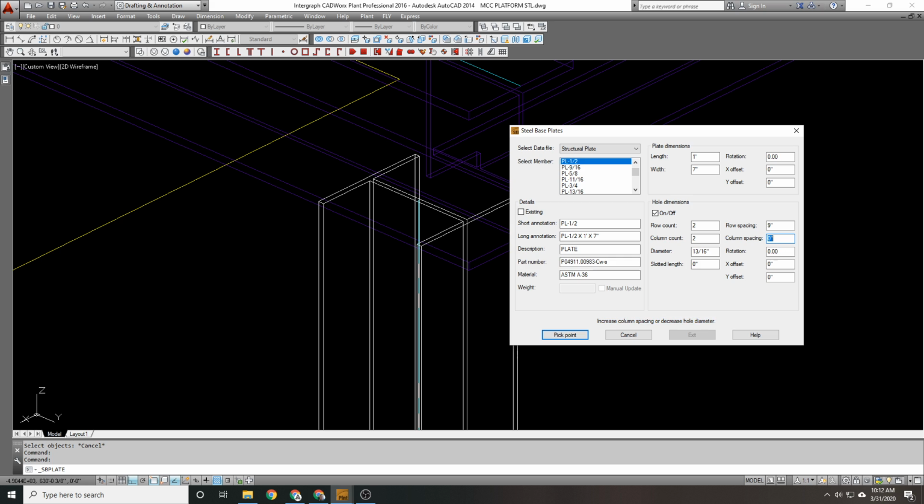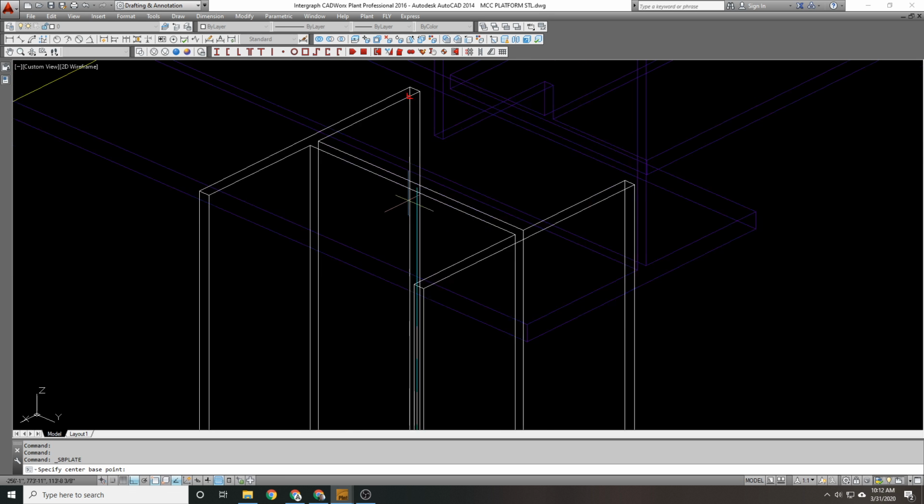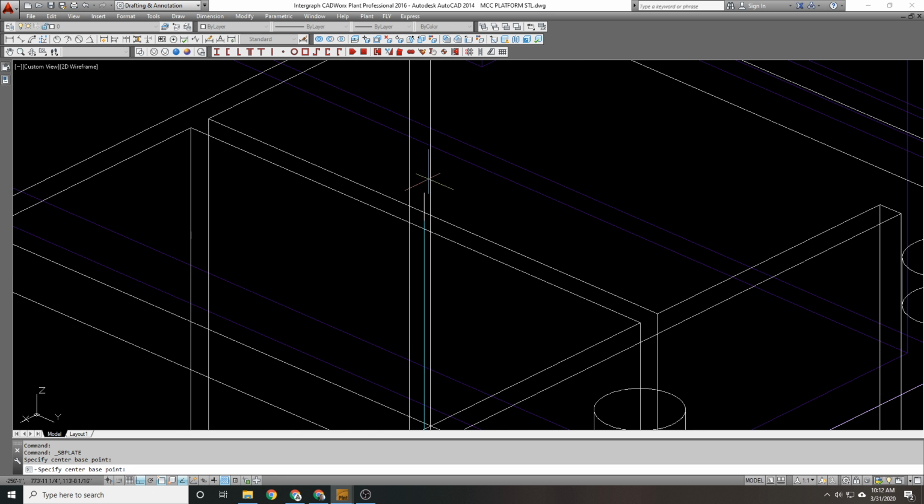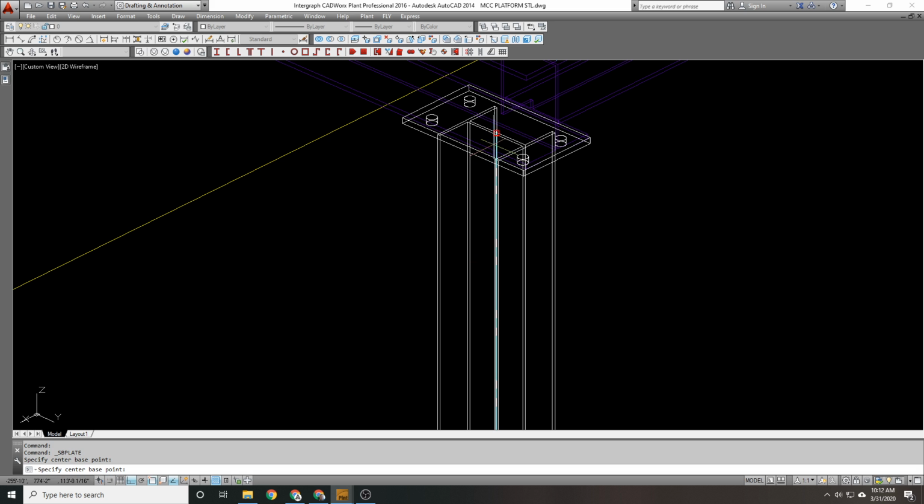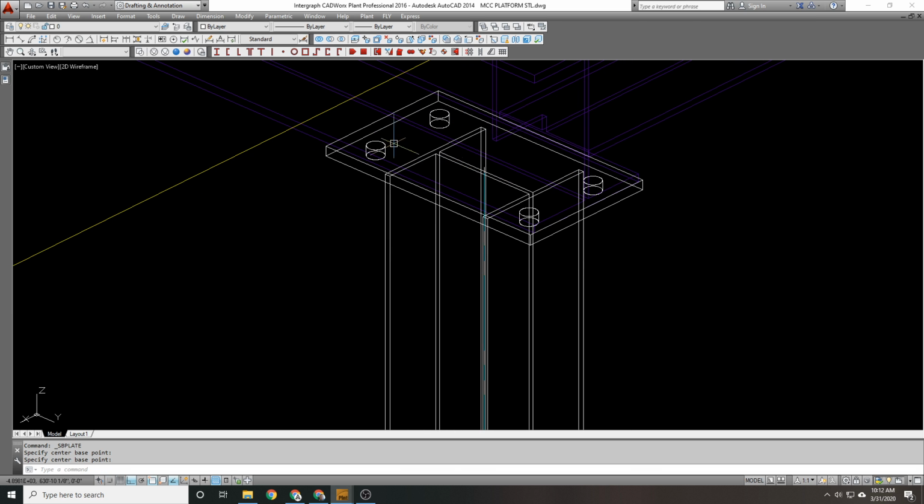It's common knowledge that it is a 3.5 gauge, but it actually has been updated. I don't know when, but if you look at the current steelbook, it's actually a 4-inch gauge for 824. It's the only beam to use that, I believe. So now that I've got all my dimensions in place, I'm going to say pick point and choose the end point of this, and it's going to bring that 615 down automatically. It just shortens it up for you.